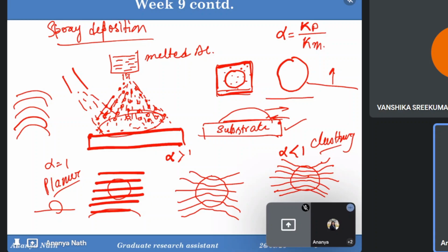For that, researchers go for higher optimization of process parameters, including more process parameters at the time of welding. They set up the welding parameters in such a way that there will be no residual stress present inside the material. Sometimes you need as-built aluminum alloys for a few applications. I do not remember the application right now, but there were some automobile applications where you have to go with the as-built aluminum alloy because of properties related to the residual stress. There you can use these non-heat-treatable alloys because you don't have to go for heat treatment. So non-heat-treatable alloys have a lot of applications and processing.